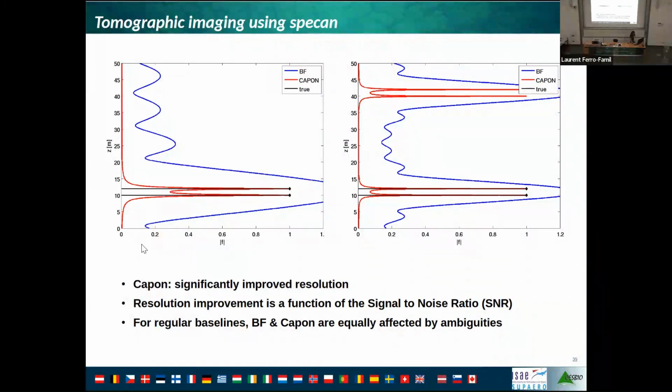This is in blue, the response of the beamformer with a very wide main lobe, okay? Because we have two targets. The targets are two objects, sorry. In radar, we always speak about targets, but I should say scatterers, okay? We have two sources, two very close sources, and of course, the spacing between the two sources is so small that the beamformer cannot discriminate them. So we have one big lobe saying, okay, there is something below it, but you don't know if you have a single target or two. And when you apply the Capon technique, you find that in fact there are two.